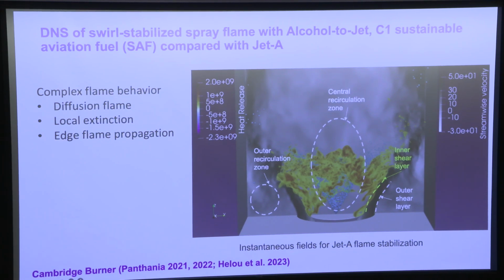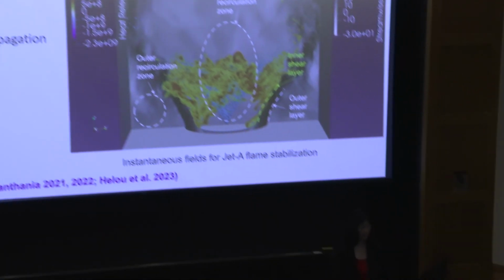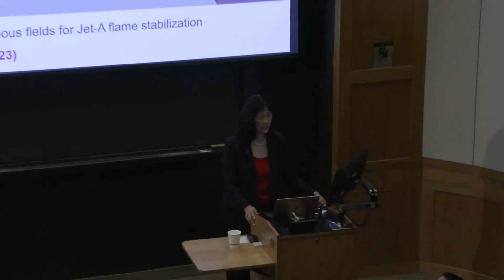And then we also see another second inner shear layer that's formed by the incoming cold air stream mixing with the high temperature products that's close to the flame stabilization location. So the interaction between the shear layers and the burner geometry generates these 2 different recirculation zones that are labeled by the white lines, the outer recirculation zone, and then the central recirculation zone behind the bluff body.